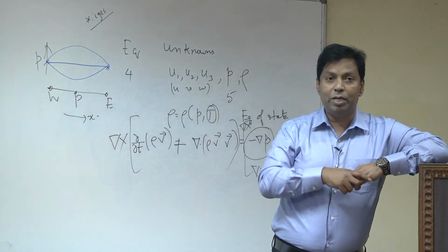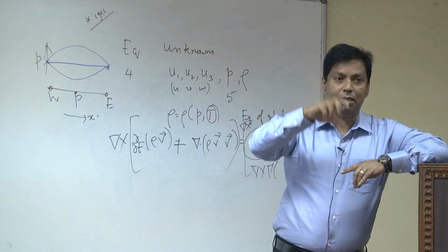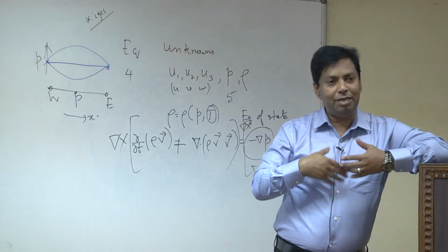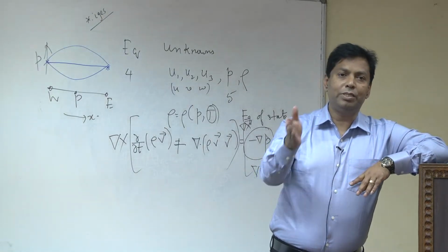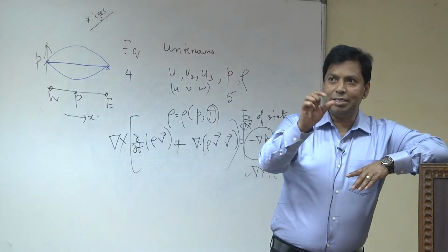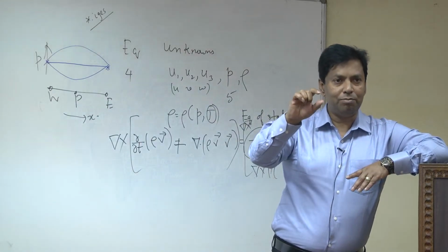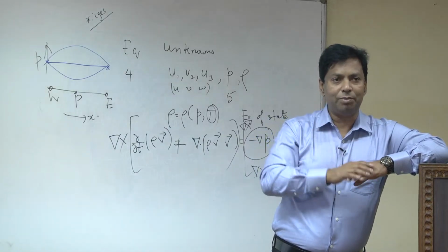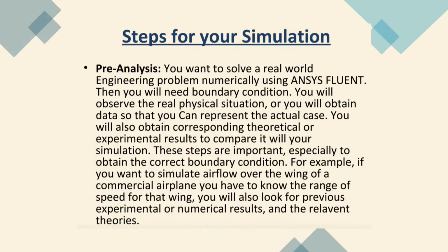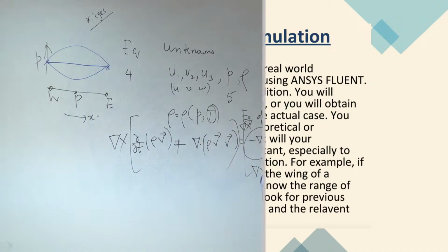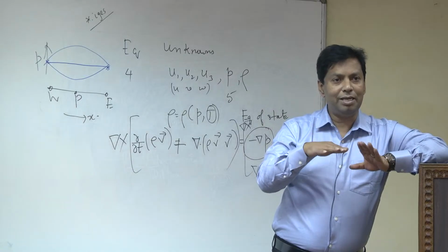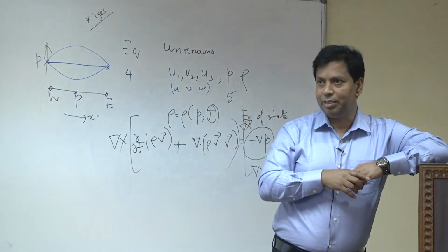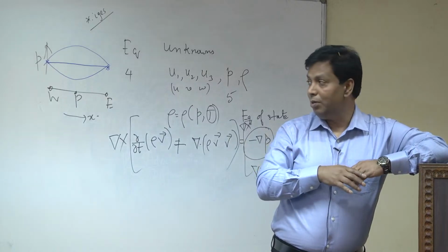Professor Chakraborty told that there is an upper limit and a lower limit of acceptance. Generally, as a CFD researcher, if we compare our result with some numerical results, we take an error of about 2% maximum. If the error is less than 2%, we accept. But if we compare our result with experimental data, we can accept up to 10 to 15% error, because, as I told, experiments have a lot of uncertainty, since there is some influence from the environment. So, we still accept it.